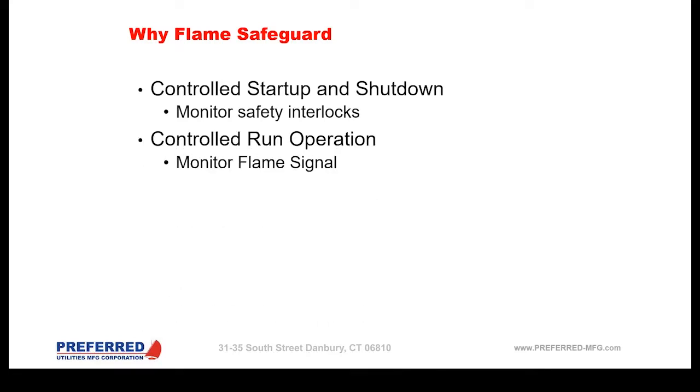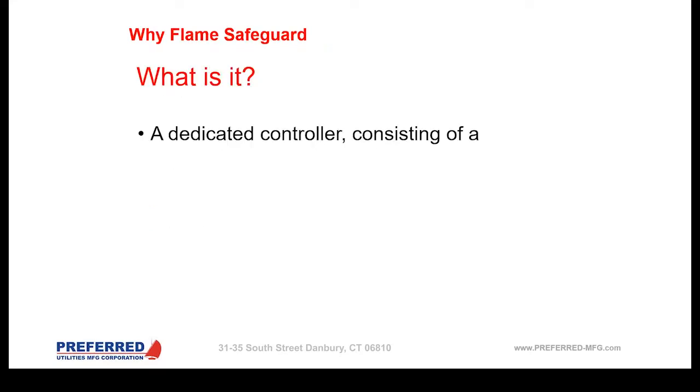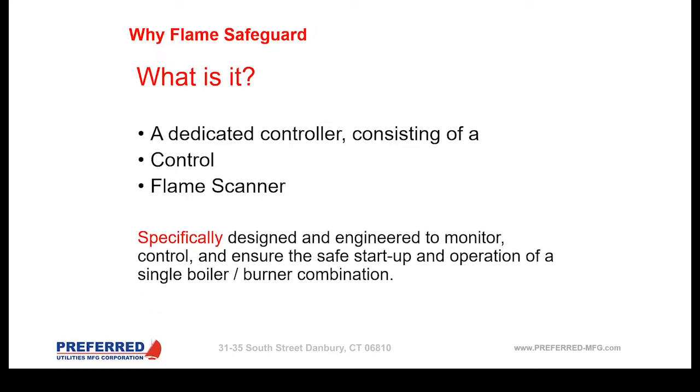So the first thing, it does perform a controlled startup and shutdown and monitors the safety interlocks. That's the basic operation. Controlled operation monitors the flame signal at all times. And of course, it's made to protect lives, first and foremost, and protect the property, obviously.